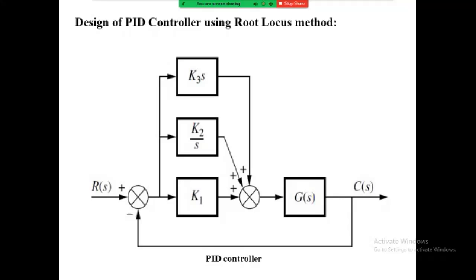As an approach, we can improve the steady state error first and then follow with a design to improve the transient response. A disadvantage of this approach is that the improvement in the transient response in some cases yields some decay in the improvement of the steady state error, which was designed first.